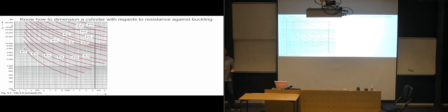So if you need to calculate this on your own, it's the very same way that we would calculate it if we were basically creating a steel support, a vertical steel support that was going to have a lot of weight on top of it. We do it in accordance with Euler, one of his formulas.